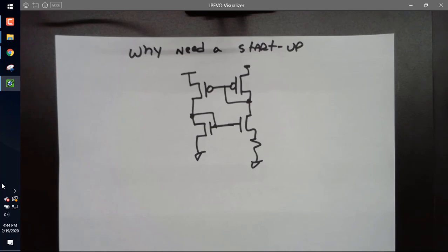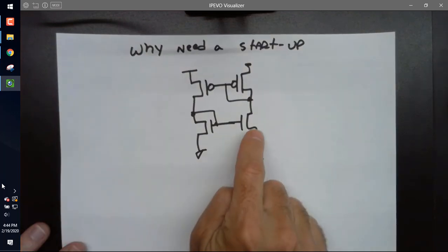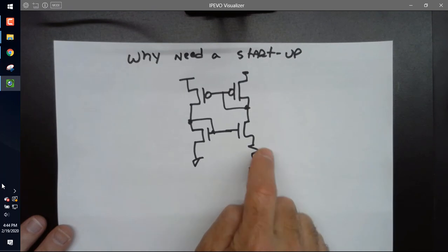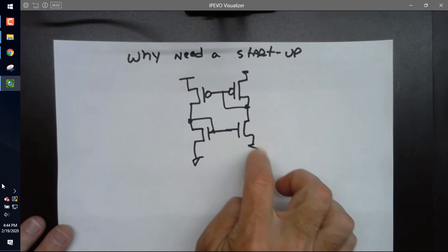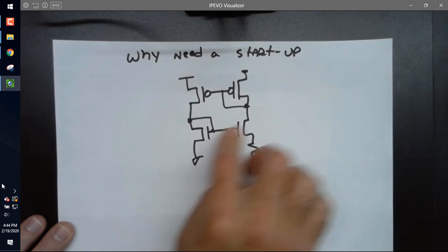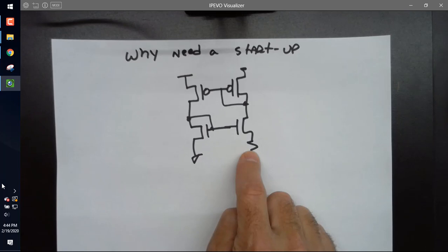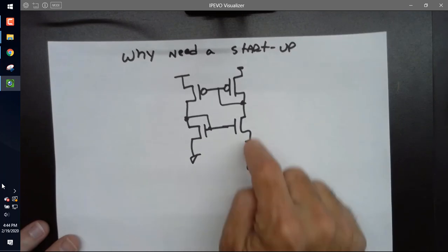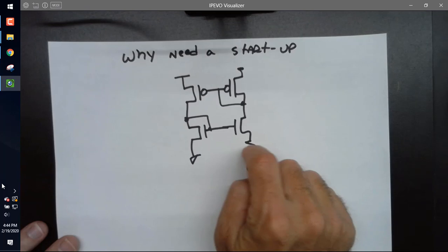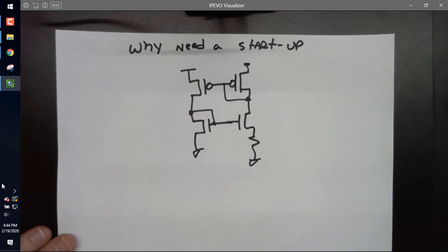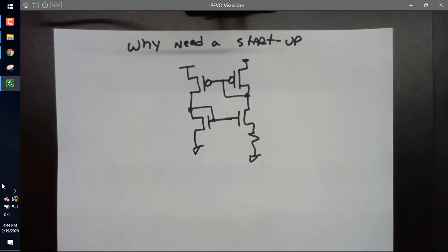The other one that is an issue that's discussed in the book is bonding this resistor out. That means connecting it to a pad and then bringing it off chip. It has a capacitance here that shunts the resistor. This is an example of a circuit with positive feedback, but by putting a resistor here, you drop the gain of the positive feedback system to less than 1 so that it's stable. But if you put a capacitor here now, it can peak the gain and it'll oscillate. I go through examples in the book about that. It's kind of an advanced topic, but it's in chapter 20 if you want to read about it.